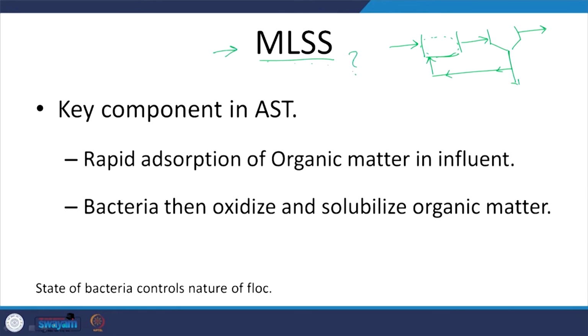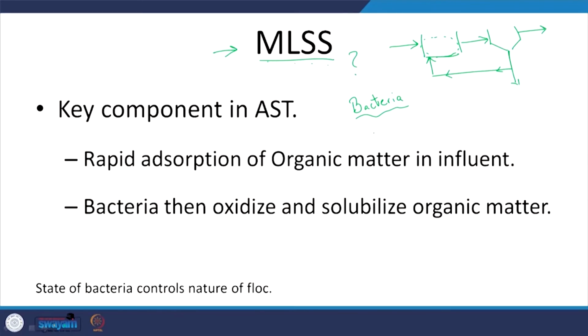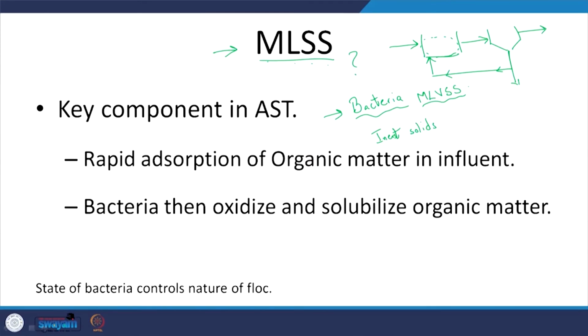So, what does that contain? Obviously, it will contain bacteria, a lot of it, depending on how you are maintaining it. What else will it contain? The MLSS will also include some inert solids or fixed solids. So, how do you distinguish between them? We try to measure that by MLVSS, mixed liquor volatile suspended solids. You have a furnace, and then increase the temperature, and then look at what is remaining. What remains, you say, is fixed, and what is not remaining, we call volatile. So, that is one aspect to keep in mind.